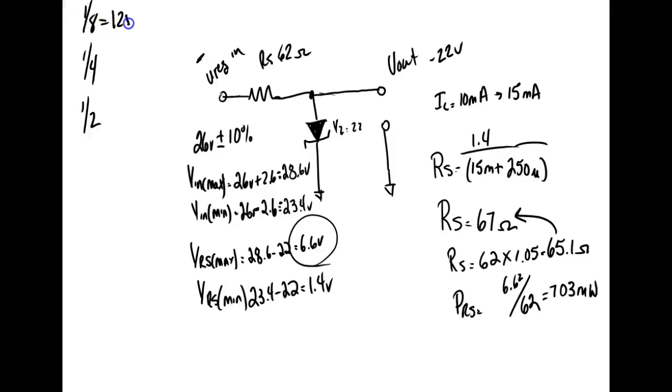Because this is 125 milliwatts, this is 250 milliwatts, this is 500 milliwatts. And then 1, so we have to use at least 1 watt. 1/2 watt would burn up. In fact, what we usually do is we go up 1 more, so we probably use 2 watts.